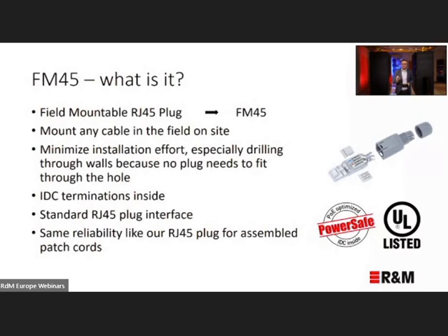This product is suitable for solid and stranded wires, thanks to IDC termination technology, which gives us very good contact. A big advantage is the use of the most common and known RJ45 standard. The installation of this plug is very fast and very easy.